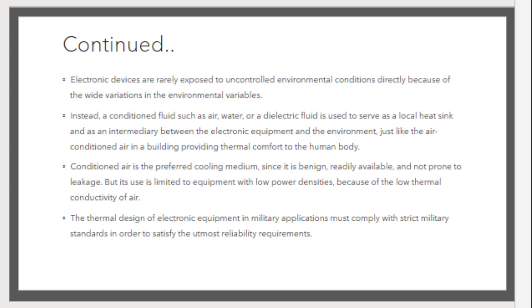Conditioned air is the preferred cooling medium since it is benign, readily available, and not prone to leakage, but its use is limited to equipment with low power densities because of the low thermal conductivity of air. The thermal design of electronic equipment in military applications must comply with strict military standards in order to satisfy the utmost reliability requirements.